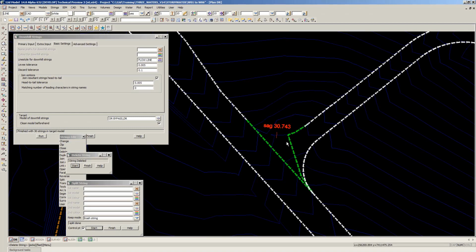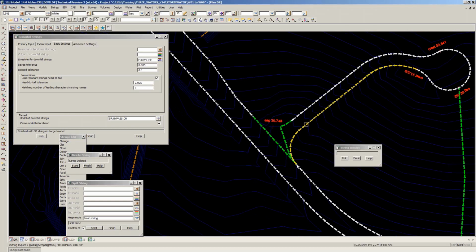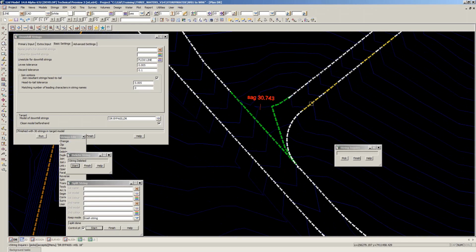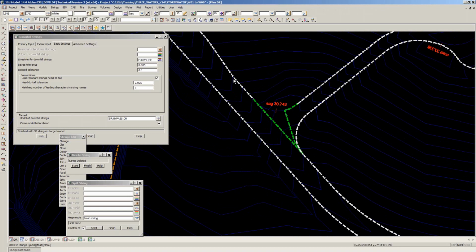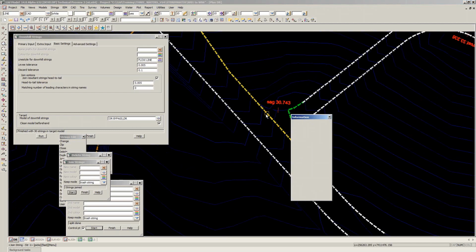and so that's pretty much it actually. So I now have one of my original grey strings. I've now stopped it there, and this is just really more of a personal preference, but when I'm modelling a T-junction like this where the side road's flowing down, you've typically got 3 approach paths merging into one there, and I like to have this through road as a continuous string there. So I would then come up and join and say I want to join that one to that one and that one to that one.